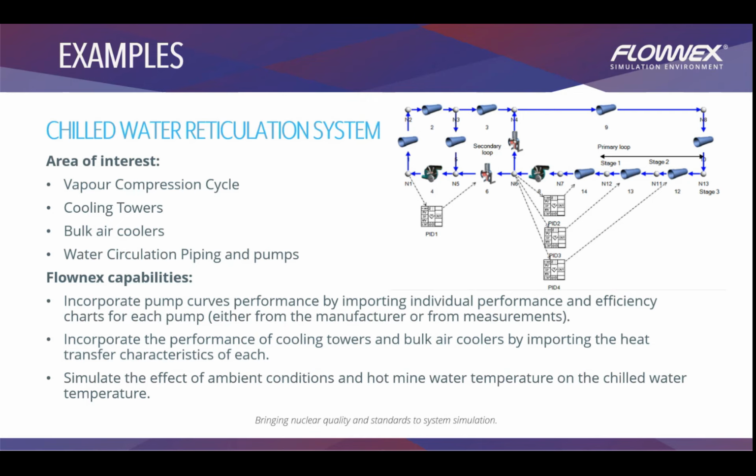Then you can also incorporate the performance of cooling towers and bulk air coolers by importing the heat transfer characteristics of each as well. It's the same as with pumps. You will get a chart, then you can just bring it into Flownex. This helps a lot with the results that you obtain, in order for us to simulate a very accurate model